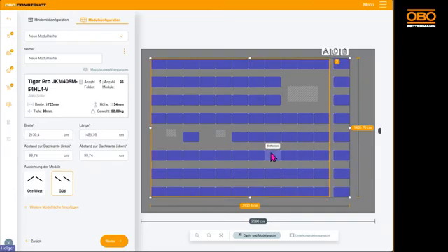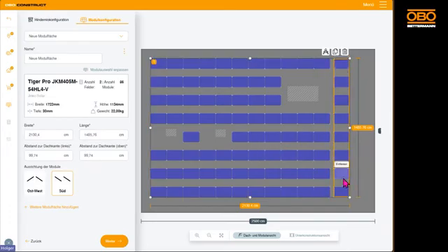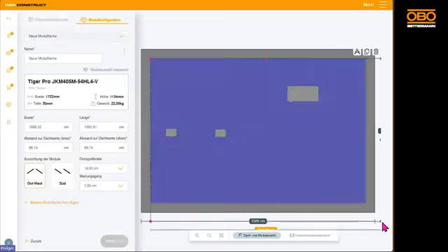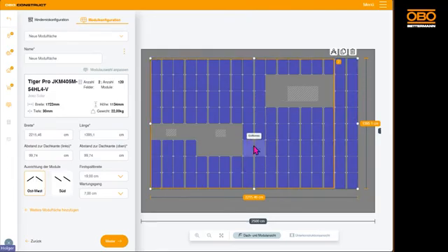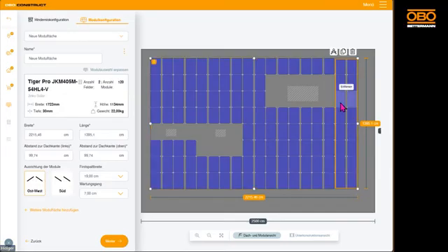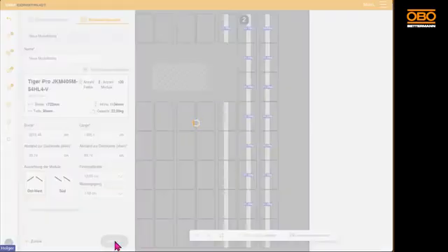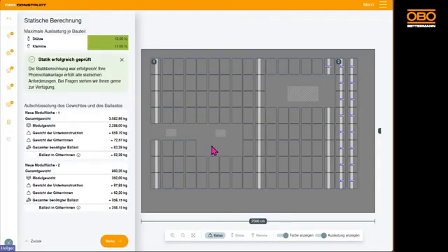And this, from a static perspective, will also need to be carefully considered individually in the later stages of the process. We'll soon observe how the small field compares to the large one. And I'll repeat it in east-west orientation. The small field tends to be less efficient in terms of ballast distribution because the interconnected components in a large field system are better positioned for distributing the loads. And that's exactly what we'll now proceed to in the next step, where we'll observe how the static analysis is being calculated for this specific setup.